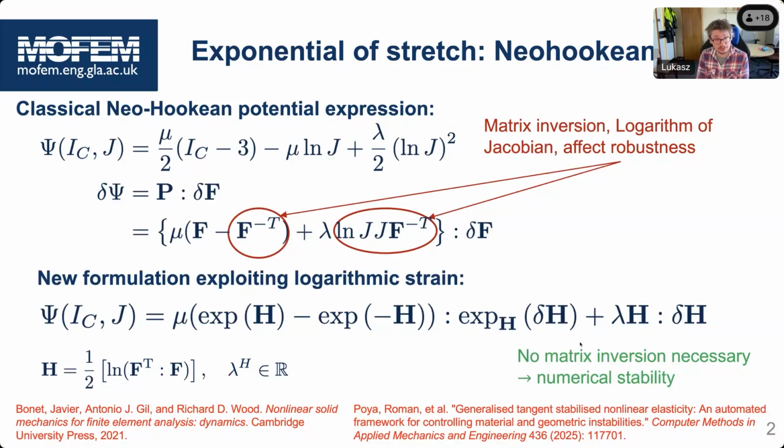I will talk mostly about large deformations and the problems associated with them, in particular when you deal with nearly incompressible materials. Very often, when you're using high order approximation orders, but also with low orders, you end up with a negative Jacobian, and you cannot invert the gradient of deformation. And you lose the polyconvexity, and that triggers lots of problems with robustness.